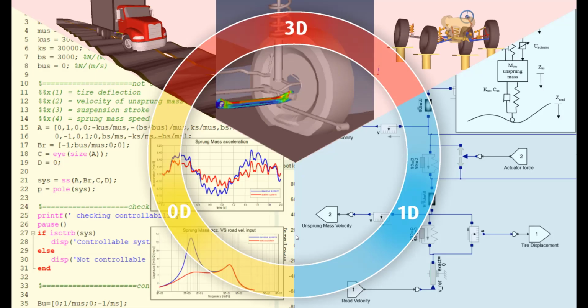This idea of modeling in a 0D, 1D, or 3D manner, I'll talk about a little bit in the upcoming slides. Just to hit on it again, 0D is the mathematical approach, or a system of equations to represent a mechanical system, let's say. A 1D approach would be that drag and drop block diagram system modeling way. And then the 3D would be if you're co-simulating with a model-based tool, a 3D model, and using that as a subsystem in your system model.